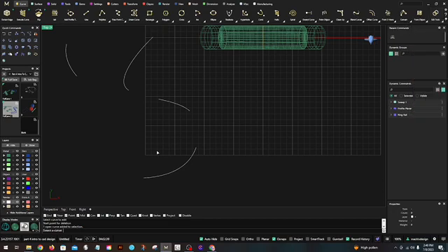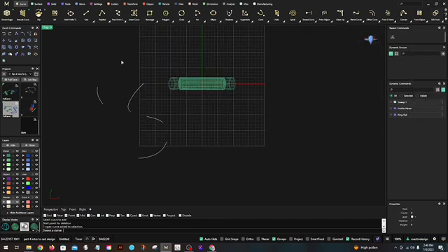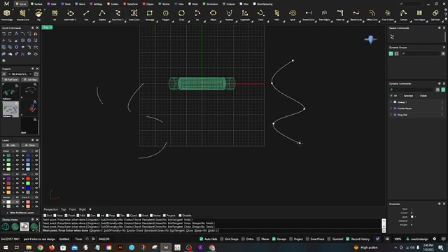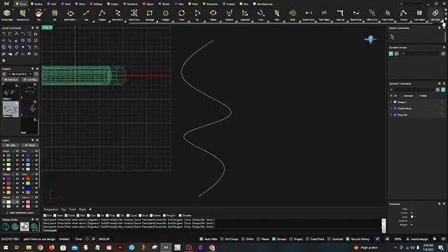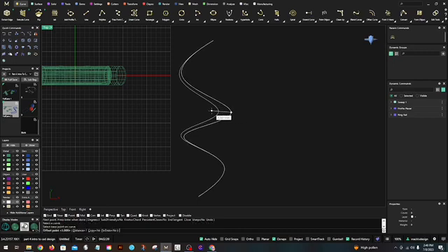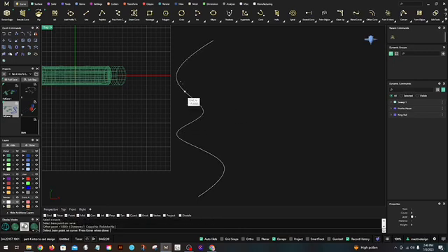So soft edit, and we're going to soft edit. Actually, I'm going to do a new curve here. One that's a little wavier. And then I'm going to come up to edit tools and soft edit. And I'm going to select this curve. It tells me down in my command line. I'm going to click on that and bring that in.